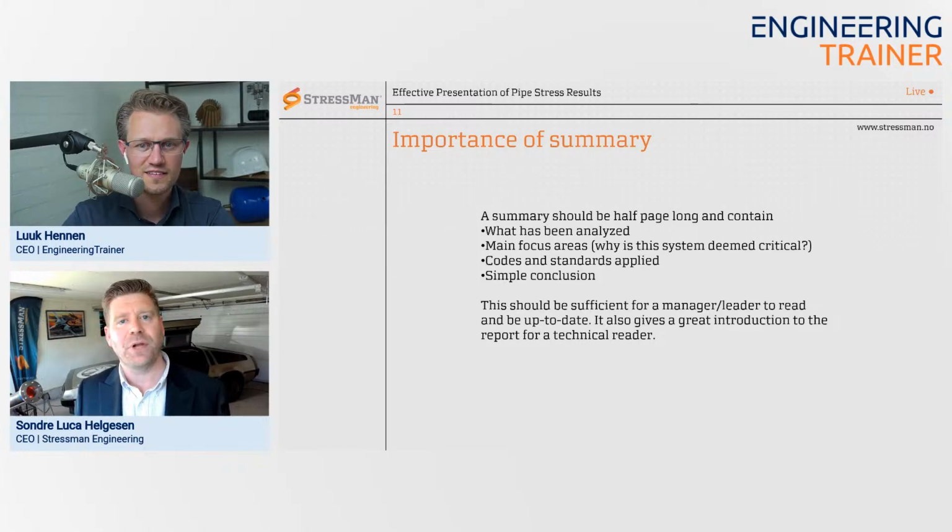It has a much more comprehensive set of equations compared to the old Appendix D of B31.3. And also there you have the stiffness of the tees and so forth. You should not get too big of a difference between FEA and B31J, to my understanding. I haven't compared too many tests against each other. I did some, also some SIFs I checked, and they were almost spot on when I ran an elastic-plastic collapse check and checked them against Tony Paulin's data.